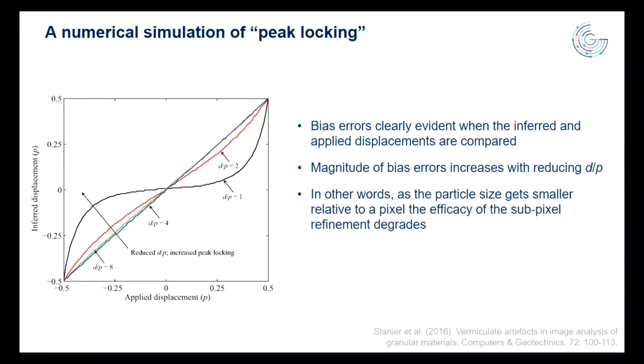So what you want to make sure is you've got sufficient particle image size. A value of 1 isn't really going to cut it here. A value of 2 is getting better, but really we want a particle image size of about 4. Any more than 4 pixels per particle, and we're wasting resolution.